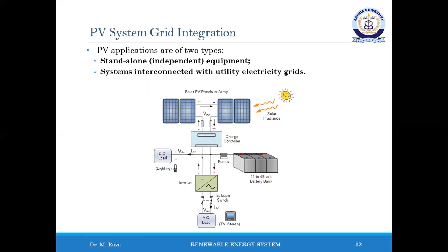The latter can greatly extend the battery lifetime. However, controllers in standalone photovoltaic systems are more complex devices that depend on battery state of charge, which in turn depends on many factors and is difficult to measure. The controller must be sized to handle the maximum current produced.